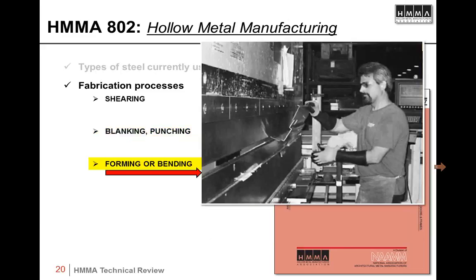The forming process illustrated here is just basically a break form operation. But on cold form steel, it can be either break form, as shown here, which is used in frames, doors, and a lot of the componentry, or it can be the automated roll form processes, which take considerable tooling but automatically forms the product, basically.